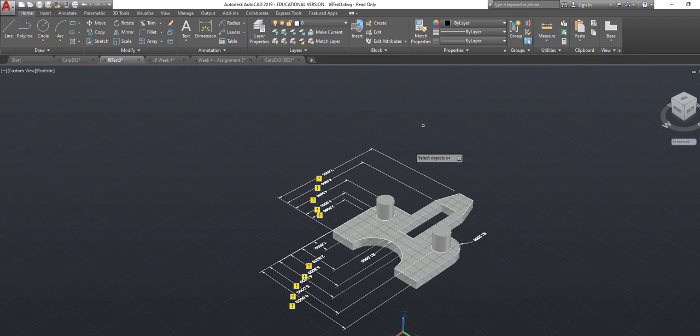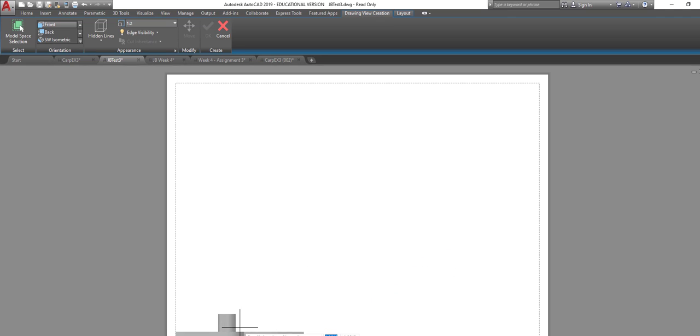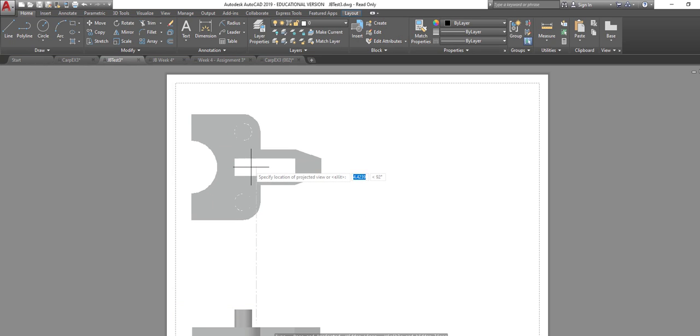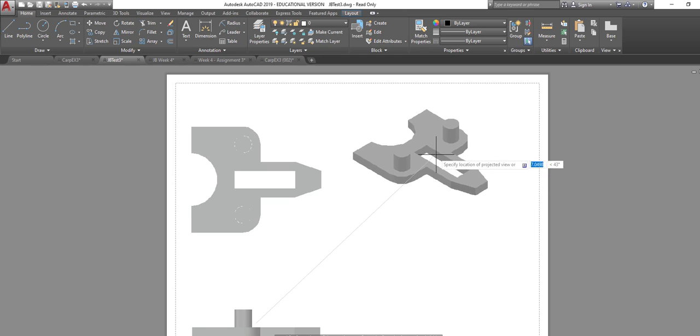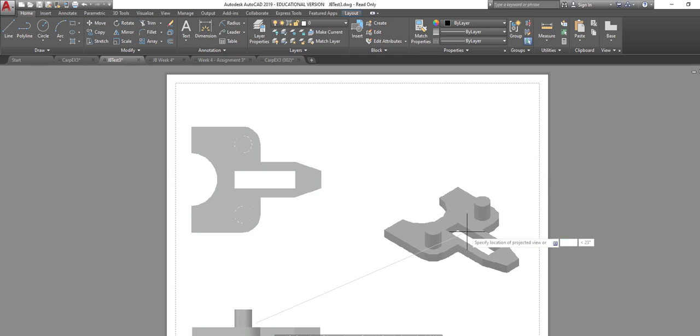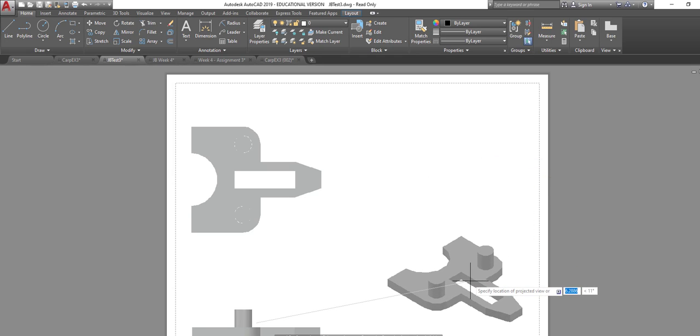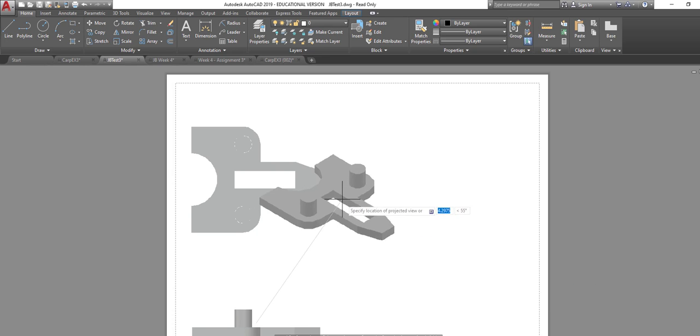Okay, let's go back and do the 3-view drawing like we've been talking about. There, enter, layout 1, yes. Okay, so we're going to do a side view so we can get our height projection. Let's exit. Let's do this one here, and then at the 45-degree angle, let's select it here because I'm going to bring my dimensions out quite a bit from there.